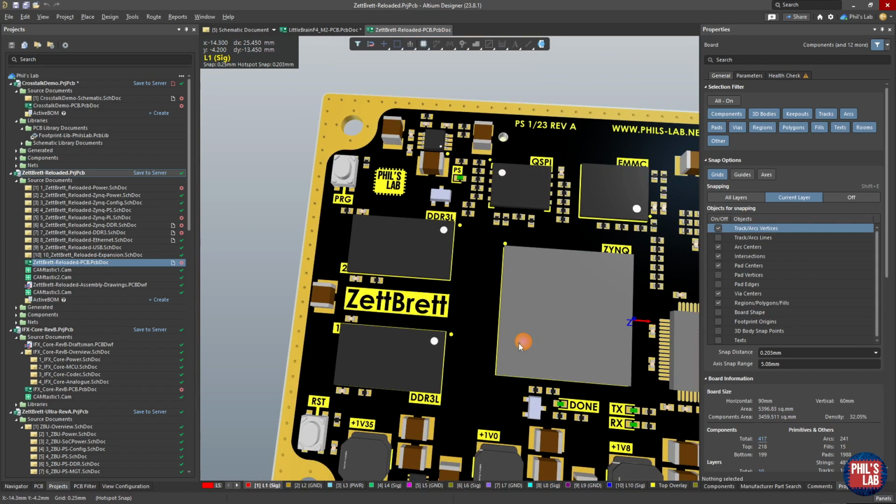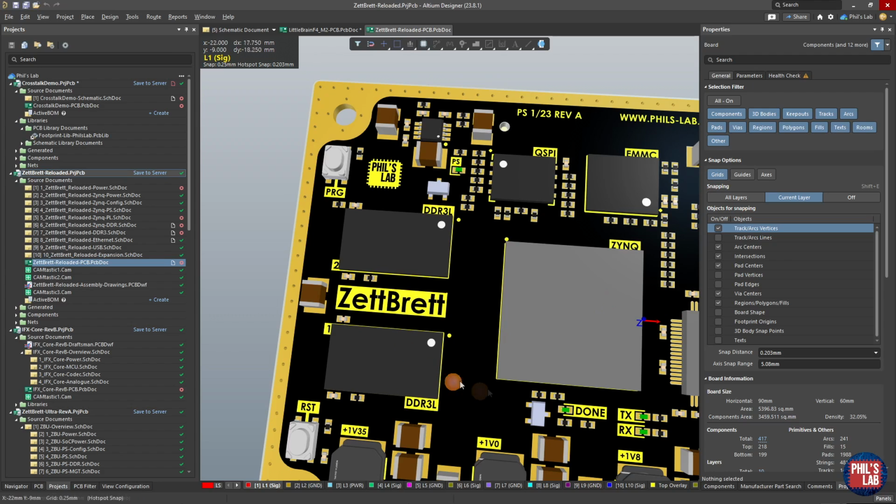This interface is very high speed, the trace lengths are above critical lengths, and therefore parallel termination is needed in this case. We have very strong drivers in the memory controller, which is needed as the termination resistors are rather low value to match the trace impedances.